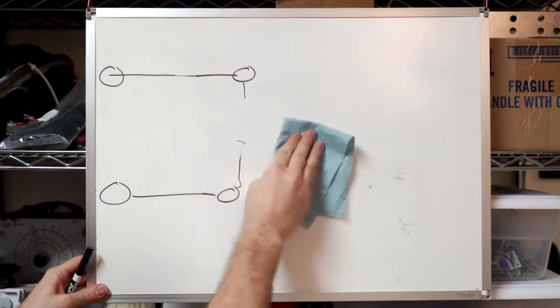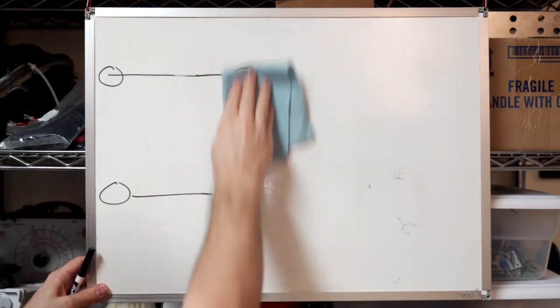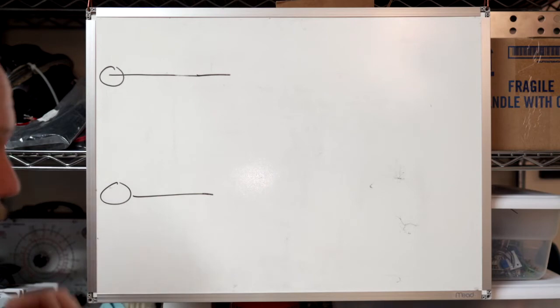Although I do actually really like to measure the output impedance of tube amplifiers by actually doing that previous sort of method. And so the reason it works with tube amplifiers is because tube amplifiers, generally speaking, have large output impedance compared to solid-state amplifiers. So, in fact, a lot of people have said, and I think this is true, that a lot of the sound of a tube amplifier is actually sort of it being imperfectly a voltage source. And so, like, the average output impedance of a tube amplifier can range wildly.